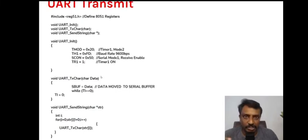I'll explain the code in the presentation first, and then we will go to the tool and try the code. First, you have to include reg51.h, to define the 8051 registers. I have declared three functions. UART init is where I configured the registers. Then to transmit a character I have a function to which I pass a character.